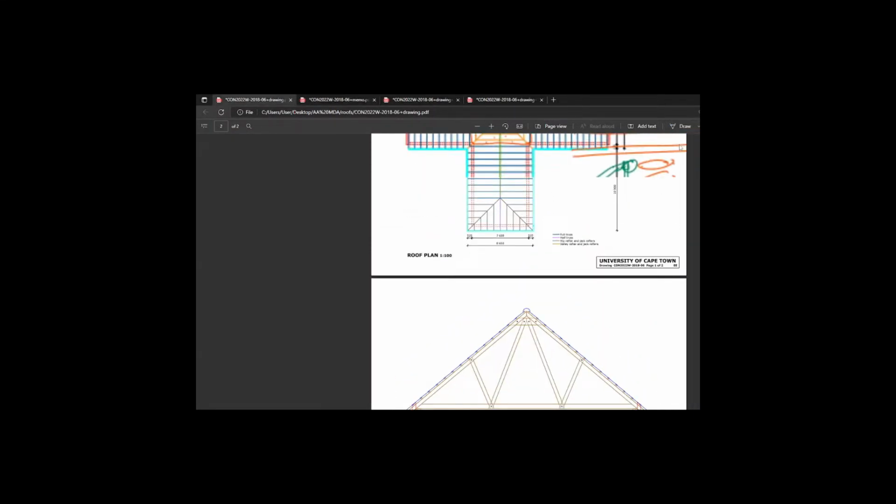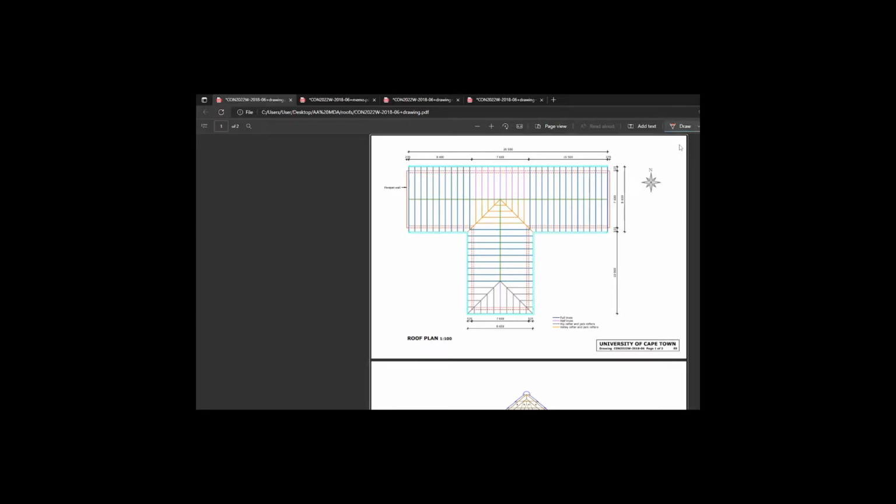Okay, this take is everywhere where we've left out, and it kind of touches on what I was saying here, is that we have a bunch of half trusses sort of floating in the air here. But how do we fix the half truss where it meets, let's say where it meets jack rafters, or where this one meets the top here? We haven't accounted for fixing this end onto the main roof structure. So this end onto this roof structure is not accounted for, and I think the same goes for whatever happens at the bottom, the tie beams. What are we attaching our half tie beams to come across? We have not taken them. And as I said previously, I'm not sure if there's anything down here. It could just be open space.